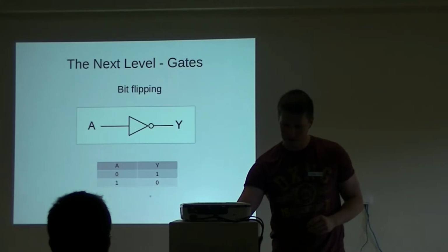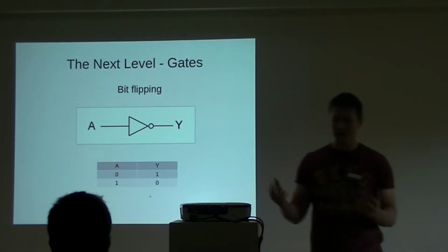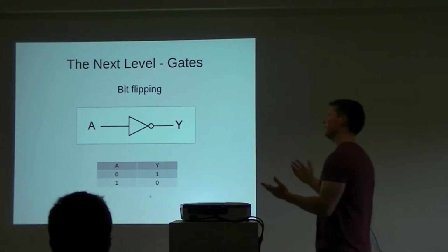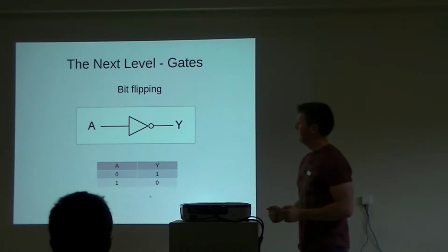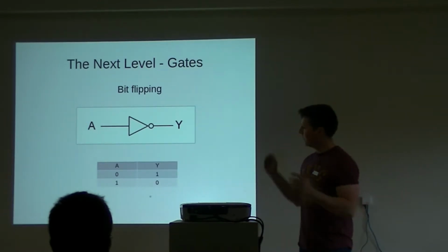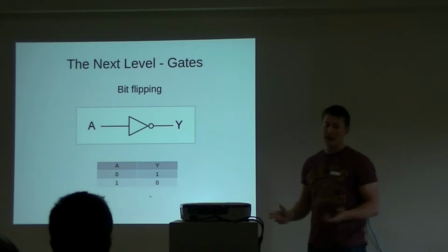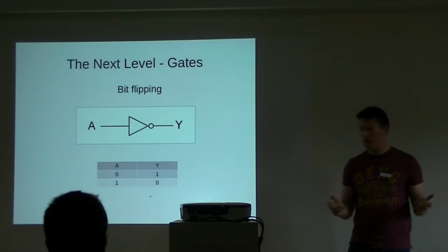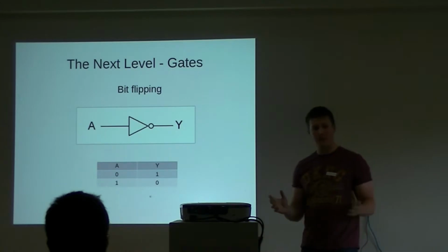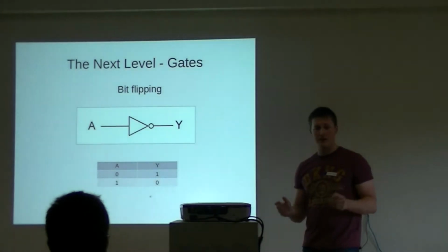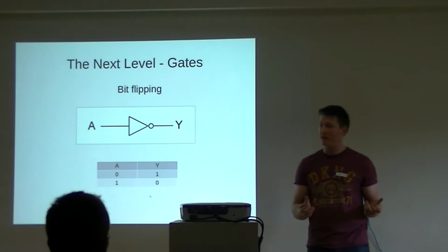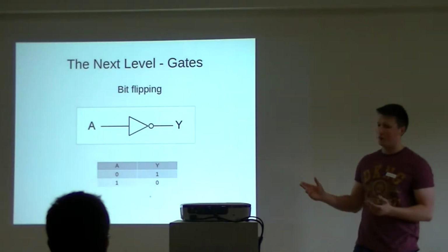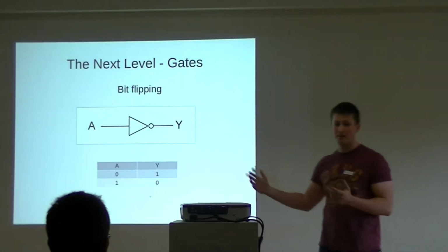At the next level, you take it up a level of abstraction. That's my NOT gate again. This is each going to be connected to other gates. So each NOT gate or each NAND or whatever type of gate you're using will connect to other transistors, other gates, and because of that capacitance you've got on each transistor, you've got to charge up each time you flip.